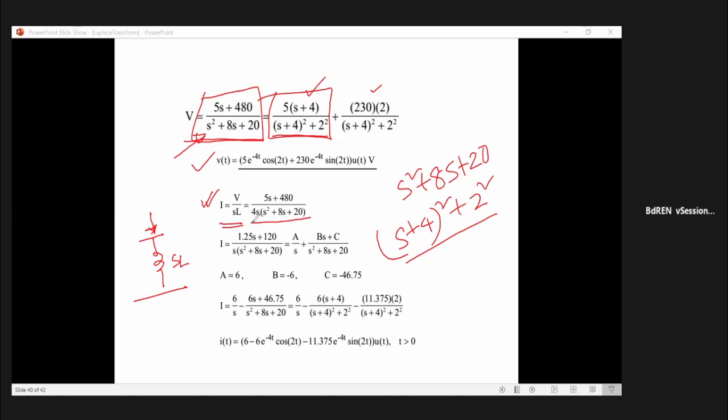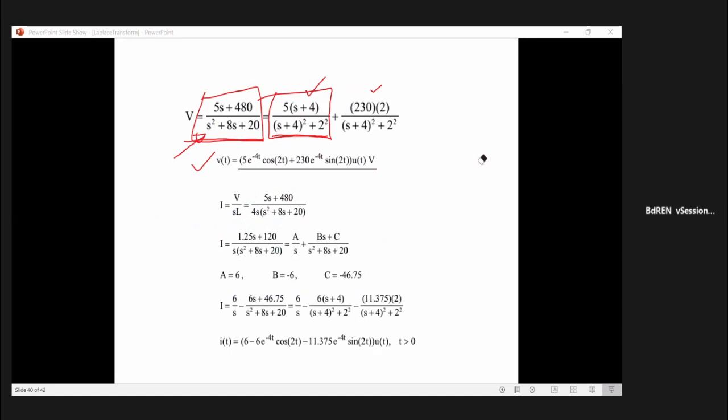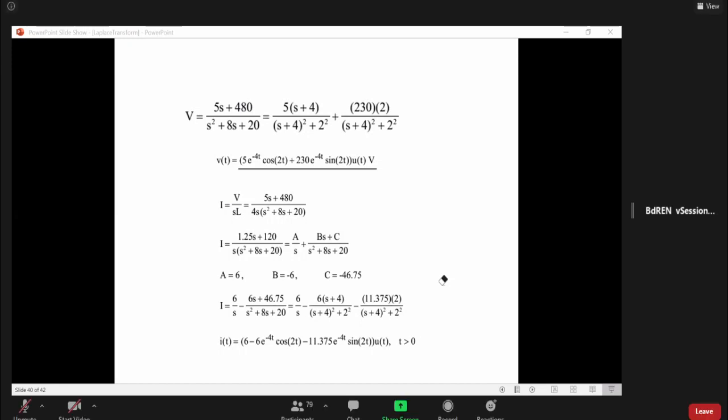If it is V by SL, then you put the value of L, and this is what that factor. Now you see that it is not a quadratic factor. Then what you need to do? Can you use your earlier thing directly here? No, sir. Then what you need to do? Partial fraction. You have to partial fraction it. After having this partially fractioned, you can again use the comparison technique to find the initial values.